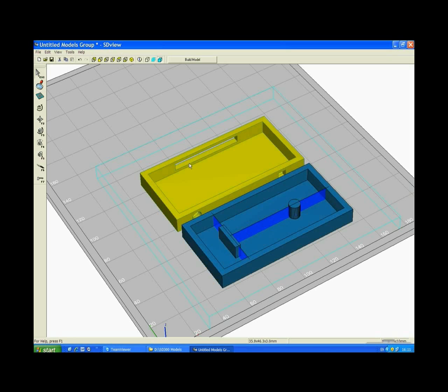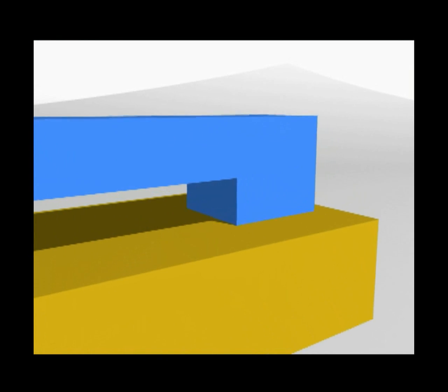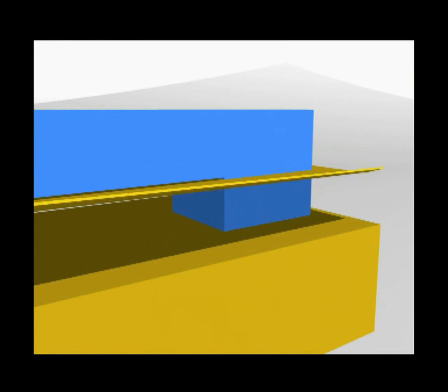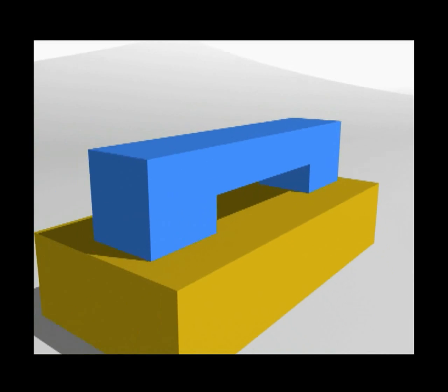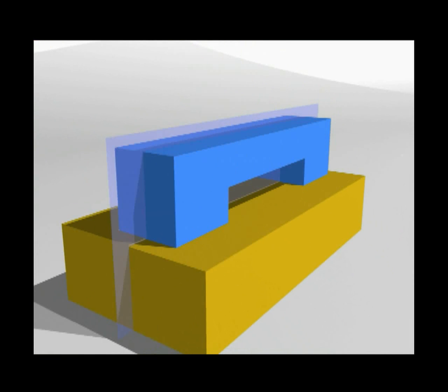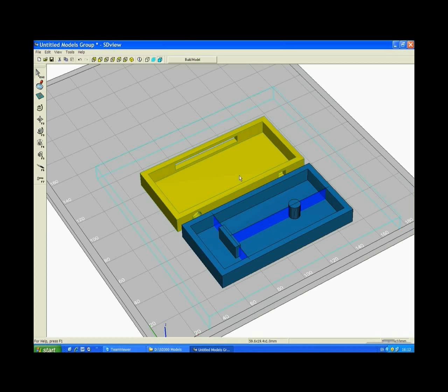The second part has openings on the X or Y axis. Openings on the X and Y axes should always be sealed to prevent excess material forming around the outside of the geometry. Excess material will always find its way into the inner parts of the geometry through these openings. Pulling the support material from the outer side of the geometry while it is still connected to the support material in the inner part may require the use of force that could damage a fragile model.